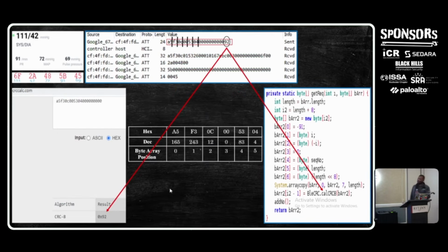All right. Finally, we've got this last thing, CRC. So CRC is usually cyclic redundancy check. Devices use this to make sure that data isn't getting corrupted. What's odd about Bluetooth is that although Bluetooth already has its own built-in CRC, they essentially made a proprietary protocol to exchange information between the smartphone and the device. In their own protocol, they added a CRC check 8, which I thought was interesting.